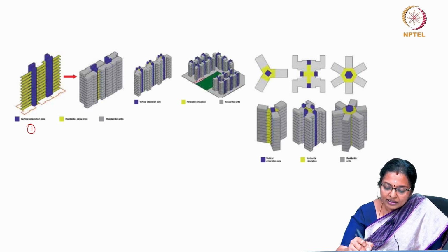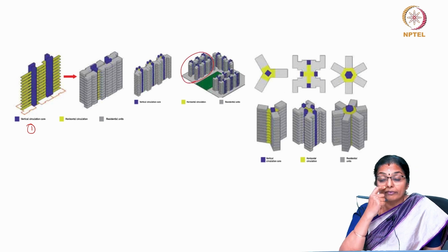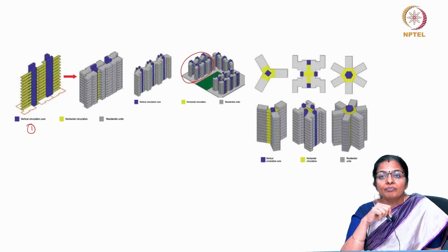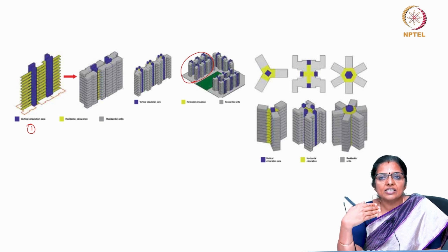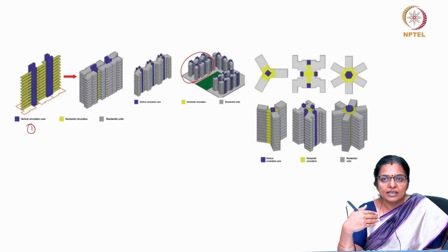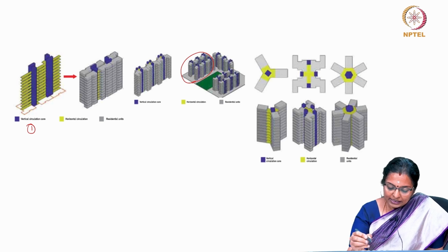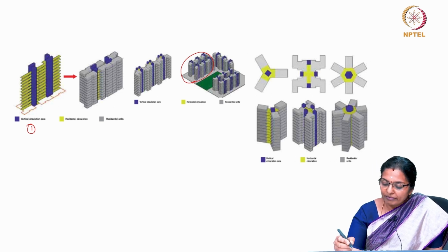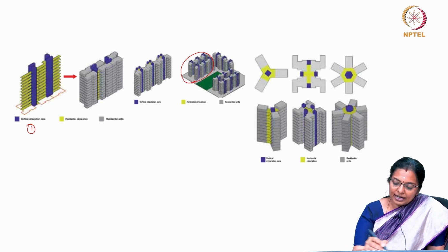So, this alone would probably work well with a hot dry climate where it is very compact and massive. It has inward facing buildings. It minimizes surface areas and openings and exposure to the east and west sun, and therefore this is a good option. So, all your options must be worked out based on your climate types. We will look at each of this and analyze now.